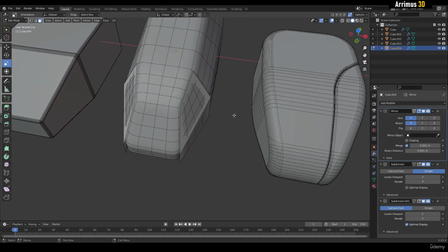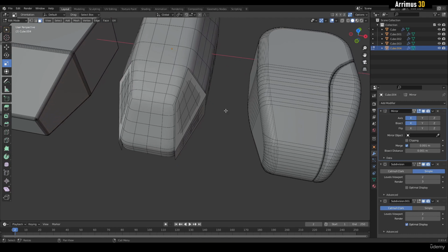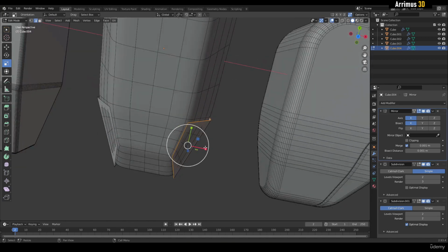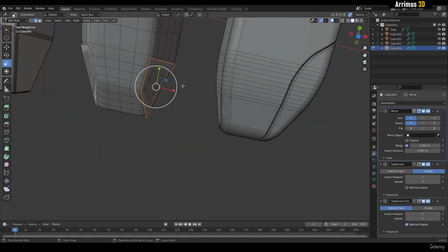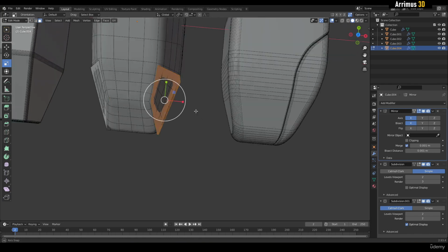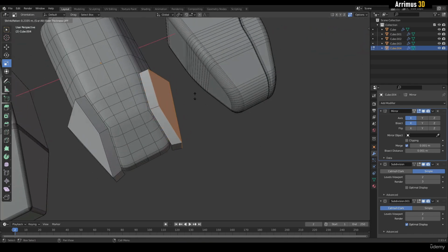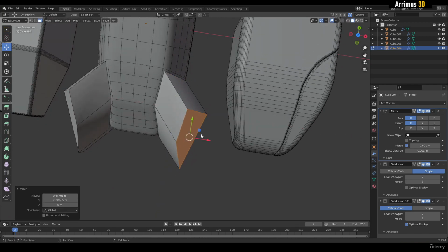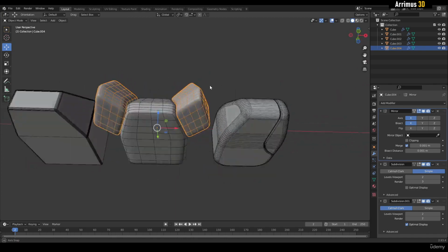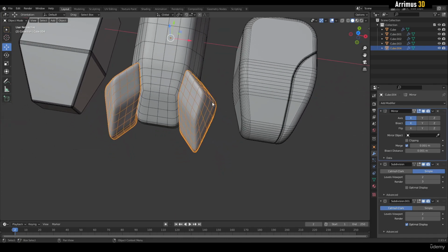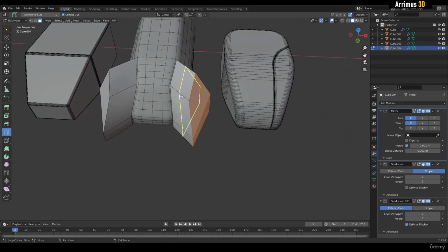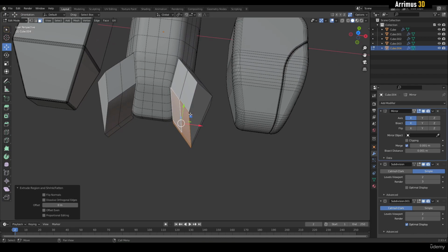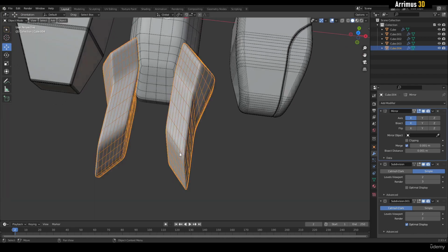All right. So I'm just going to go into edge level, A, deselect that, extrude, right click. Actually, let's just select everything, and do a small little inset here. I mean, extrude, and move this like so. So let's say we're creating some sort of mechanical toes or mechanical foot, for example, right? So we kind of got that. I insert this. Sometimes I like to extrude, right click to move back to the original position, and just move it out myself.